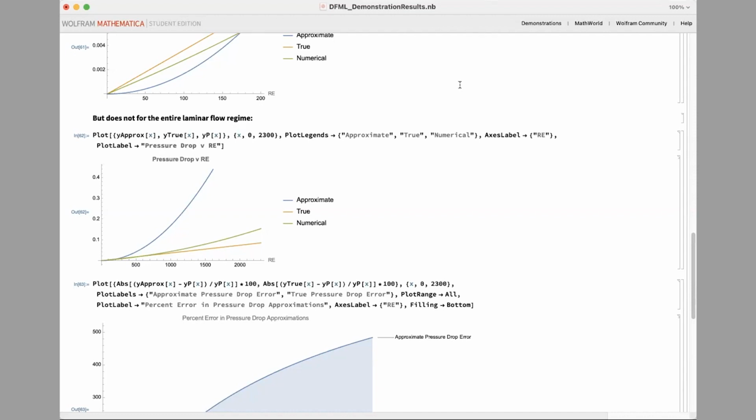So like the application of the sudden expansion is that, yeah, so we're just trying to show that if you really wanted to be accurate about your pressure drop in something like a sudden expansion or a contraction, which is like in every valve or pipe fitting, you would really just want to apply Mathematica to do like a quick simulation, because that analytical expression is just so incorrect.